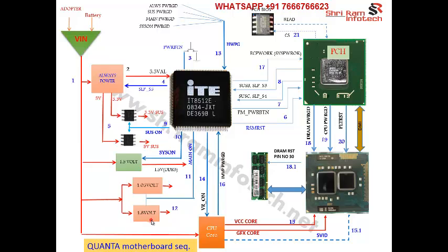Now all these pulse width modulators generate their power good. They are gathered together at this terminal, like always voltage, suspend voltage, main voltage, system voltage. All the voltages' power goods are gathered together. They are connected to each other, and that cumulative connected terminal is called HWPG. The HWPG means the signal. If here is 3 volt, that means all your power streams are okay, except the CPU.